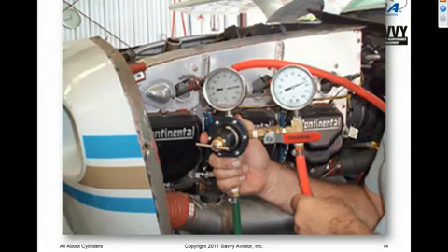And we have another gauge at the other side of that orifice. So when we turn the air on, the cylinder is pressurized to 80 psi. And if the combustion chamber had zero leakage, if the valves were sealing perfectly and the rings were sealing perfectly, the combustion chamber would reach 80 psi, everything would be at equilibrium. The airflow would stop, and both gauges would read 80 psi. But of course, there's no such thing as a leak-free combustion chamber at the very least. We're always going to get a certain amount of leakage past the rings,